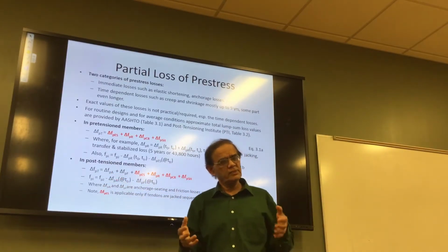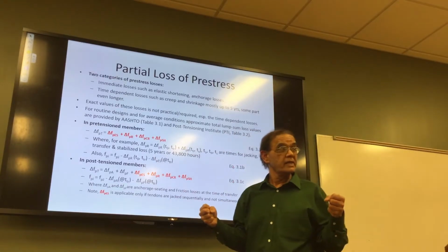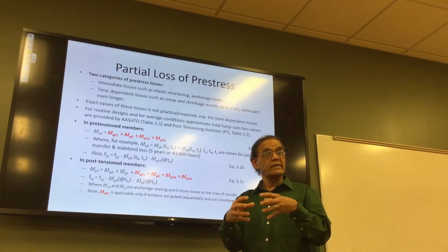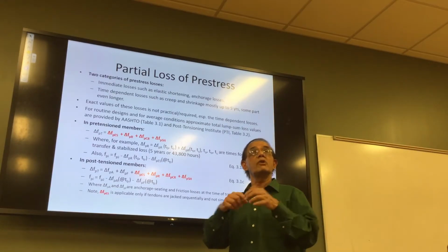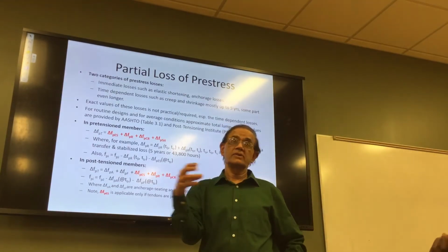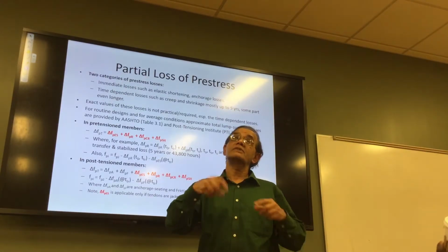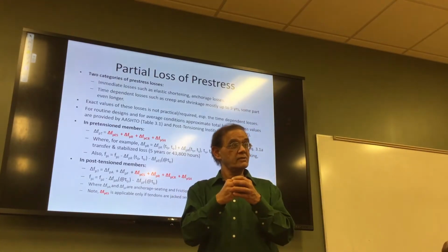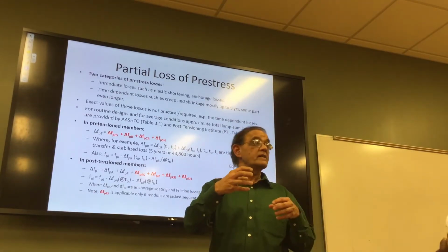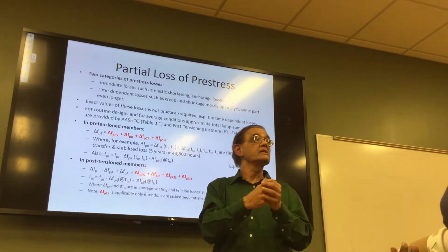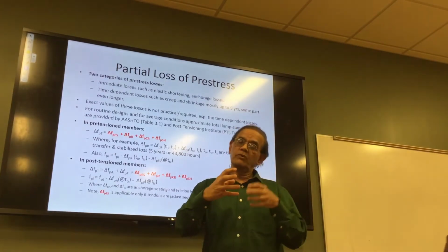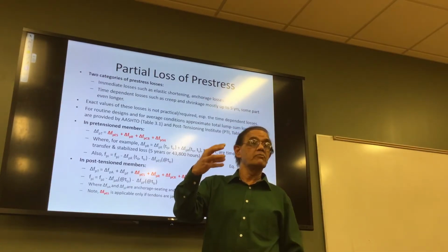So how does that happen? You're stretching the wire, and then as you relax, there are wedges gripping the wire, and the grip happens because the shape of the body at the end is conical. So you have a cone, and you have a 3-part piece inside a cone, right? And so as you pull in, the one that is gripping the bar now is seated. But it takes a little bit of loss before the thread on the inside really bites into it.